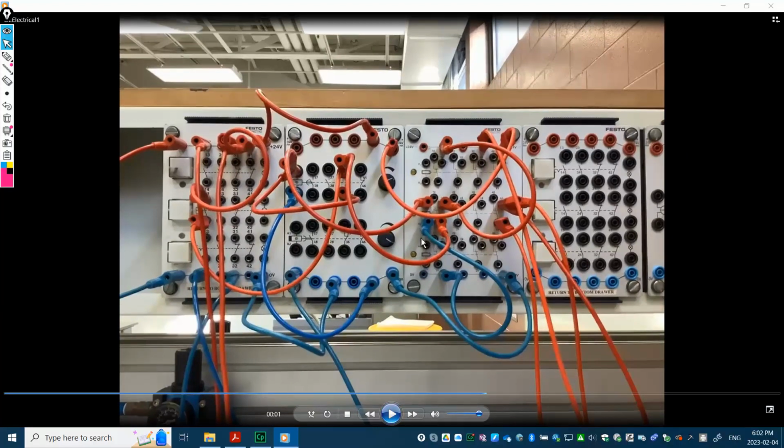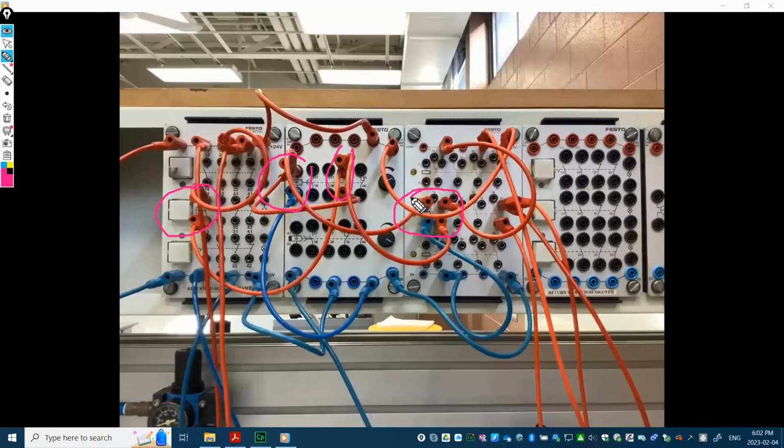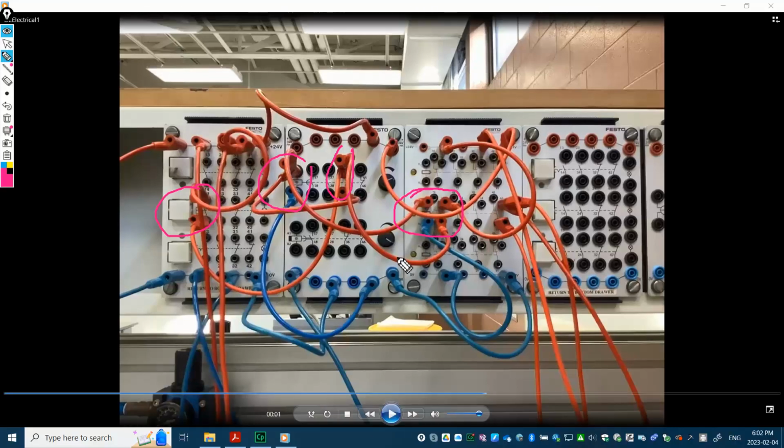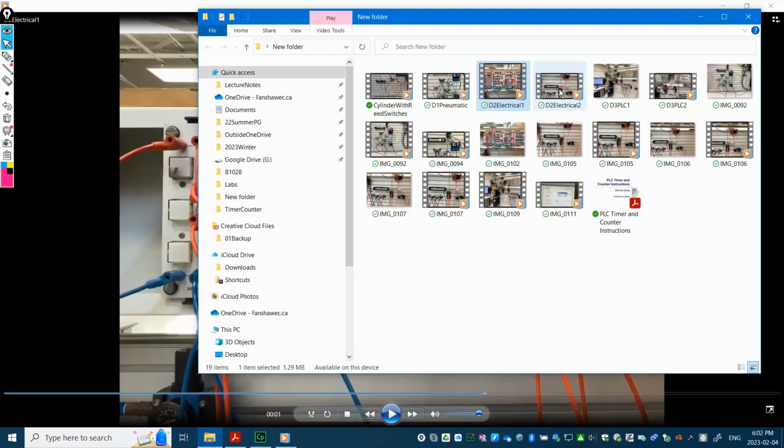Sorry about that. So as you can see here, we have the electrical connections, right? That's the push button I use, and then there's an on delay, that's the coil, and that's the contact, right? Normally closed, timed open, right? That's the symbol. This is the IEC standard. Then I also use a control relay, according to the circuit. So I built it there, and this is the electrical circuit part, right? Let's look at the second part.